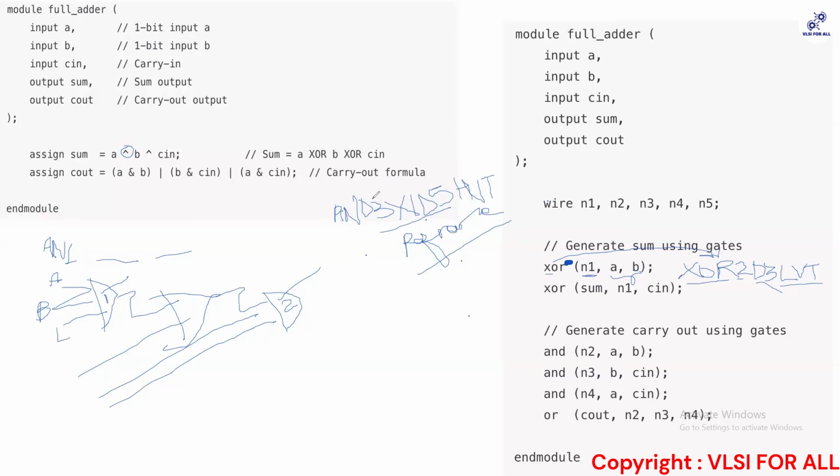But how will the reference name be, ma'am? Like the instance you have given here? See, very basically, reference name is nothing but whatever name the cell has in your library. The one which is present in your netlist is nothing but your instance name. The tool understands it in your design. It doesn't only have an instance name, it has a ref name, and then what it is all connected to. It has both of them.